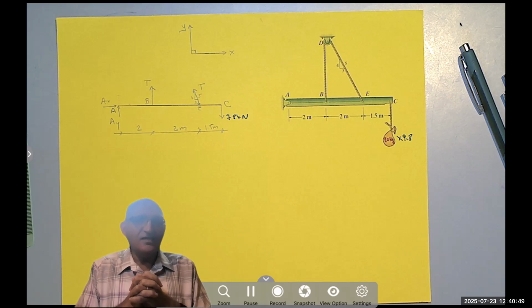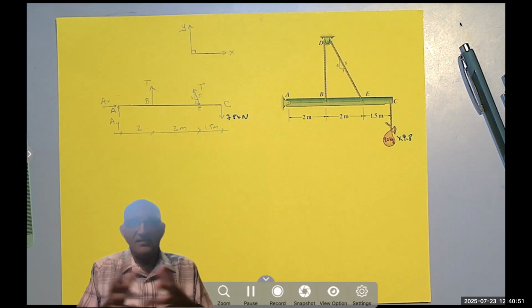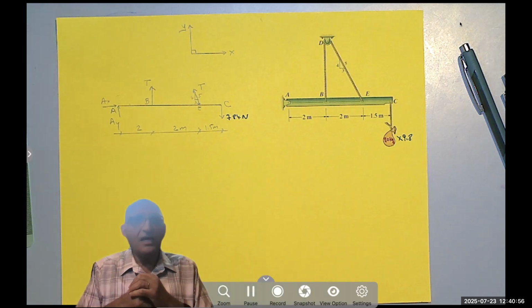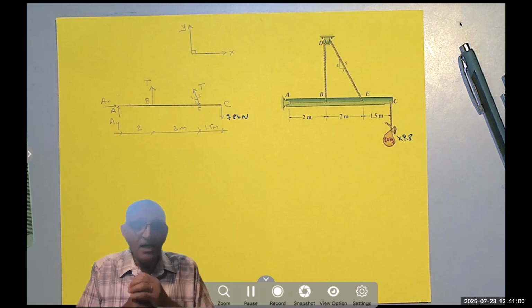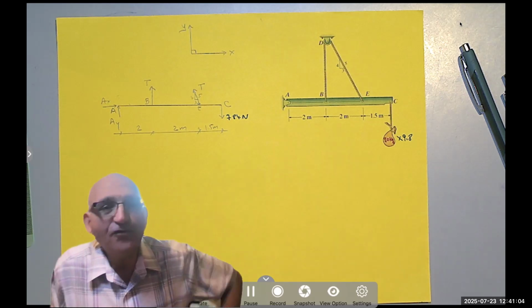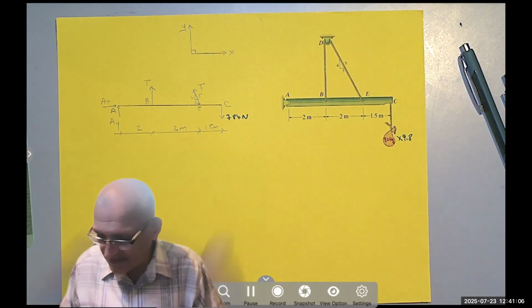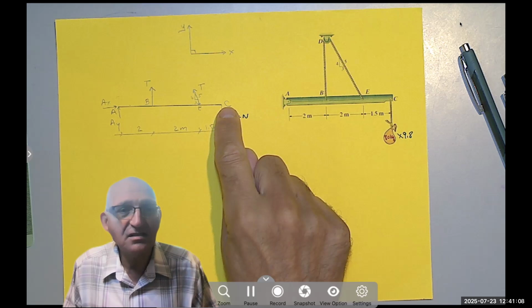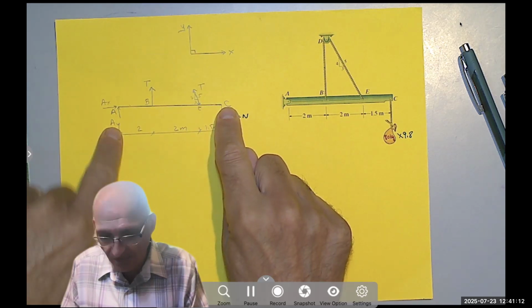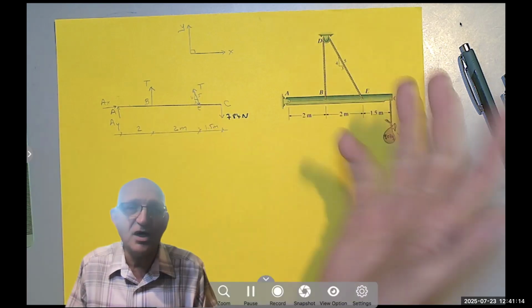So most likely, as in many problems, I should start by taking the moment. You take the moment where at least two forces intersect. It doesn't make sense to take the moment about C because the T will have a moment about C and the Ay has a moment about C, still two unknowns.